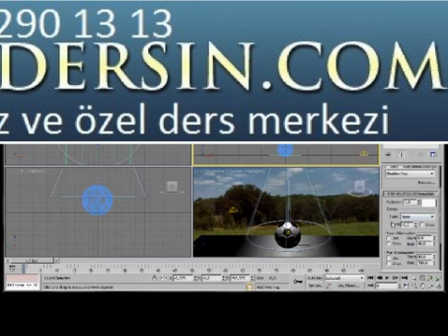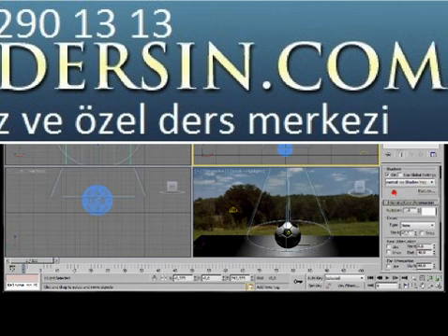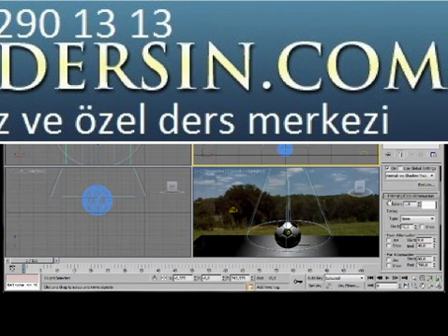Let's go to the modify list, enable shadows, mental ray shadow map, intensity we're going to change to 0.7, decay type we're going to choose inverse square.